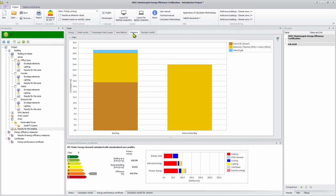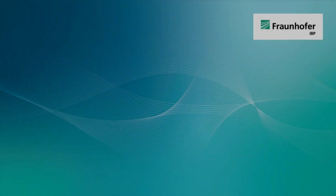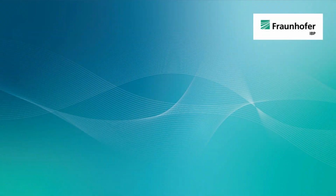The next step would be the EPC of the building, but this is shown in a separate video. This brings us to the end of this tutorial. In this video, you have learned how to enter a complete non-residential building. We started by creating the structures, moved on to the building envelope, and divided our building into zones. We then set up a hot water demand and used the HVAC wizard to set up all the necessary HVAC systems. After that, a small photovoltaic system is installed.